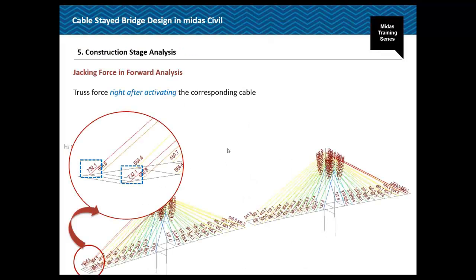So in the forward analysis, again, what is the jacking force? The jacking force is the same, so we can check the jacking force using the truss force function in MIDAS Civil. In the case of the forward analysis, right after that cable is installed, at that time we can check the cable force, the truss force.